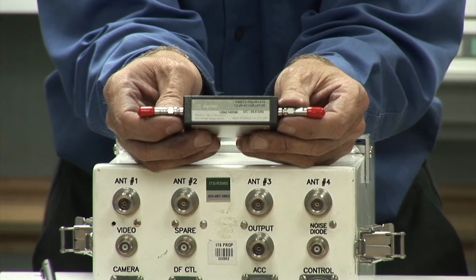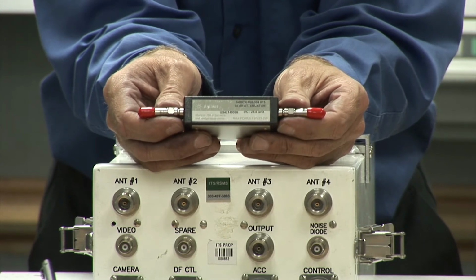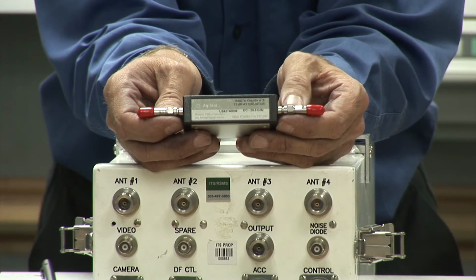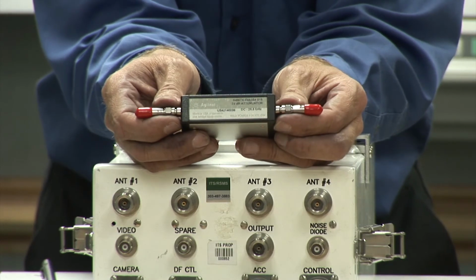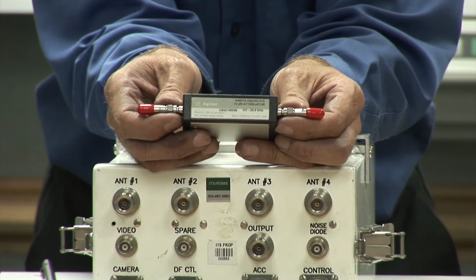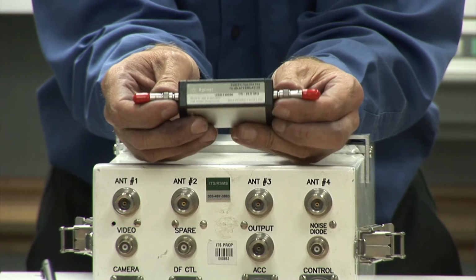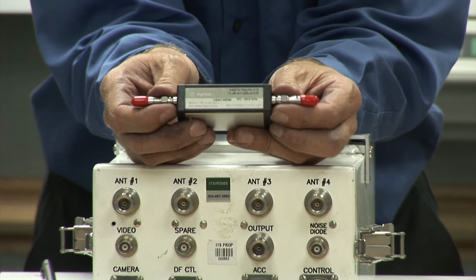First of all, at the front end of the measurement system, we typically put in an attenuator which can go anywhere from 0 to 70 dB. This is one of the attenuator types that we use, and this attenuator is electronically controlled so that we don't have to operate this thing manually. We can operate it in a certain sense manually, but only via software.